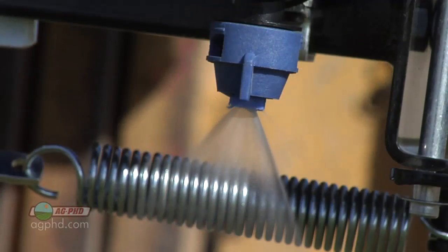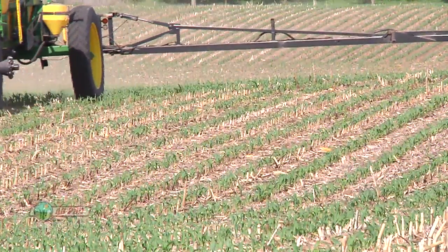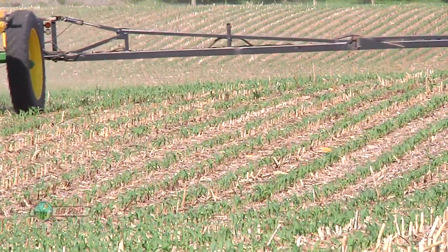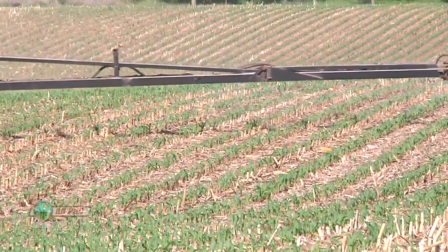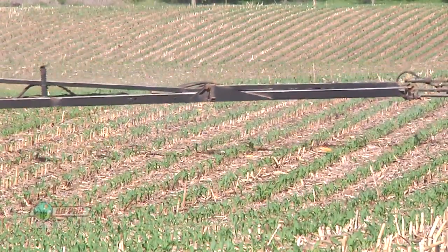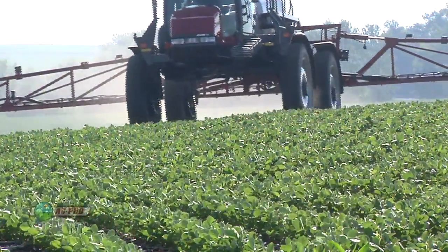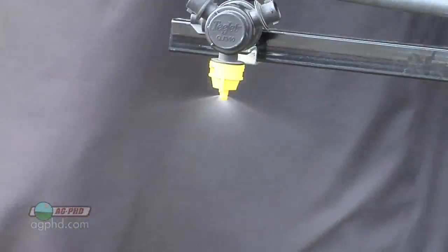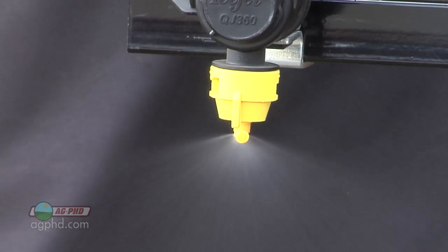We don't want to have an erratic nozzle out there that's either wasting product or just not doing a good job hitting the weeds we want to hit. Now, unfortunately, I can't give you a set guideline to tell you, well, if you get 50 acres, if you get 100 acres per nozzle out, you absolutely should be replacing that. I don't know, because it depends on what type of product you run through, how long the product sits in that nozzle, the type of nozzle that you got in the first place, the material the nozzle's made out of. So there are a lot of factors that enter into that.